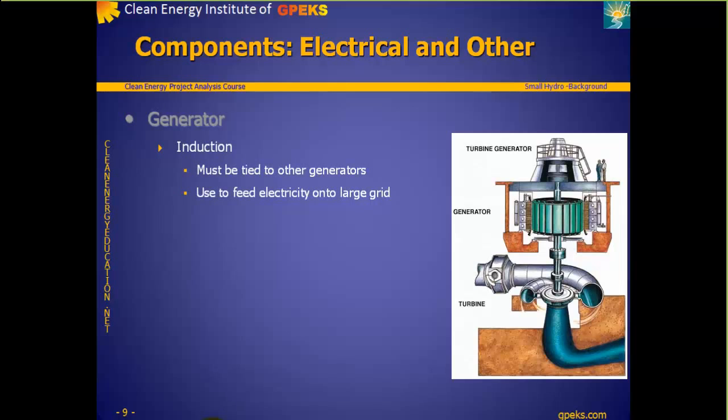The alternating current sets up a rotating magnetic field. Unless the cage spins at exactly the same rotational speed as the field, the field will induce a circulating current in the cage. The circulating current in the cage results in a second magnetic field which opposes that of the electromagnets. In practice, this means that if a turbine is attached to the cage and exerts a torque on it, the cage will spin slightly faster than the rotation of the magnetic field, generating an opposing magnetic field. This opposing magnetic field will be seen at the electromagnets as an electromotive force that adds energy to the grid.